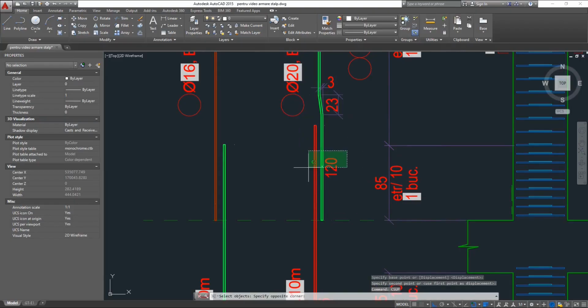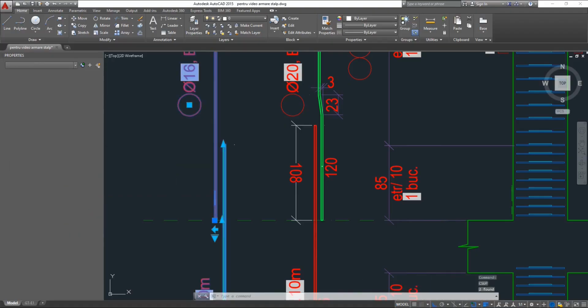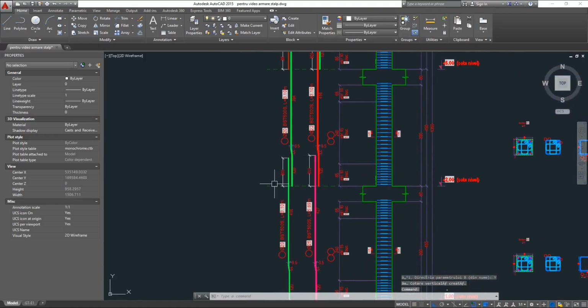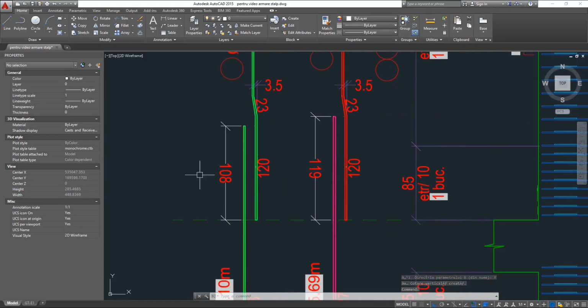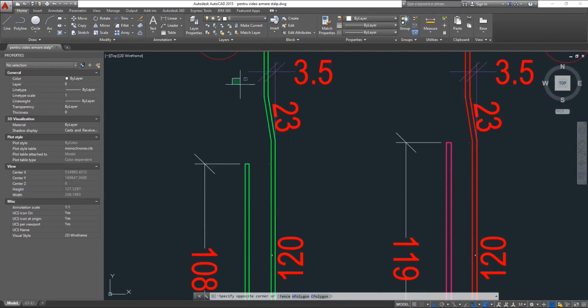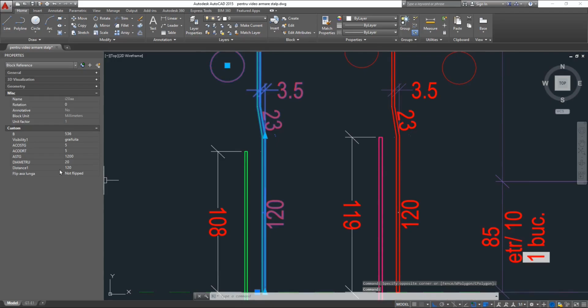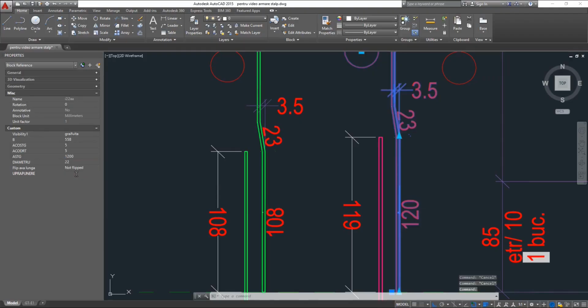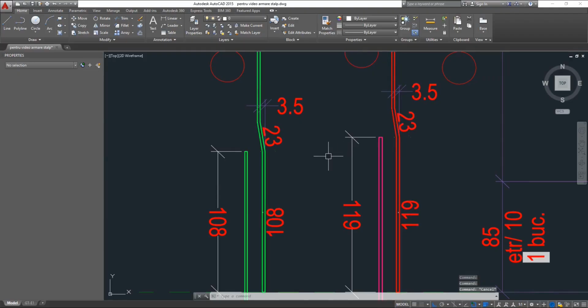We can dimension this overlapping. Again with a special command, and we can equalize these values, meaning we are going to bring the crank on the top of the other bar. And we're going to do that parametrically. Small adjustments.